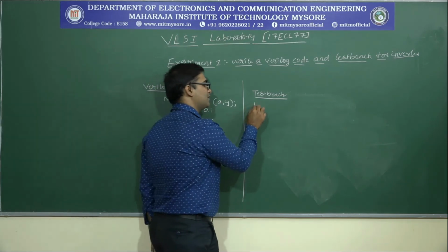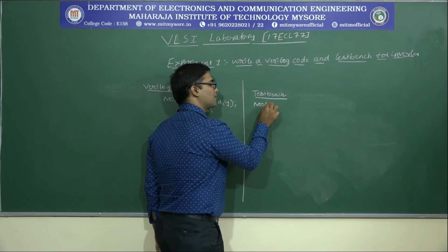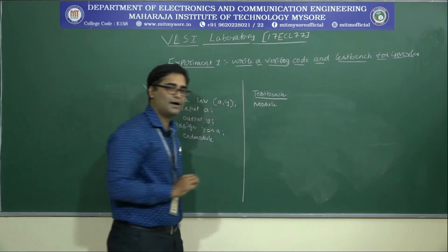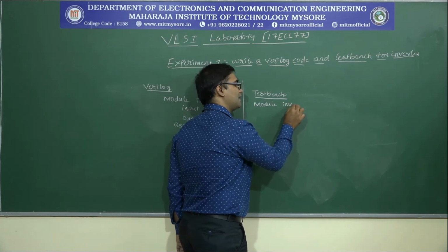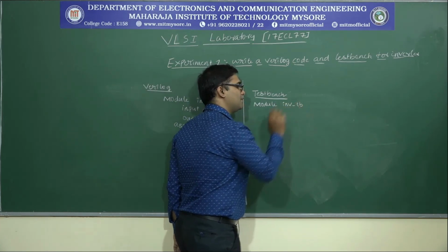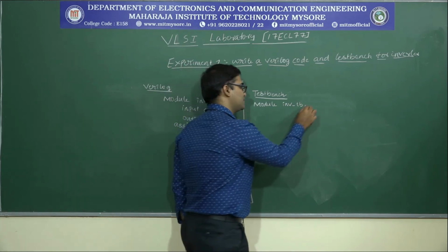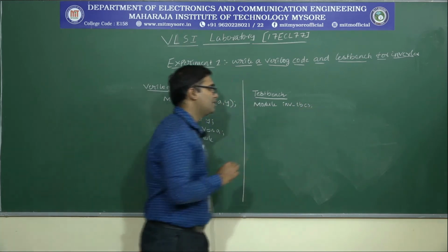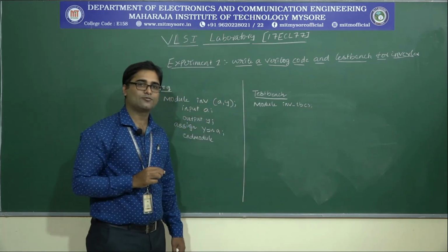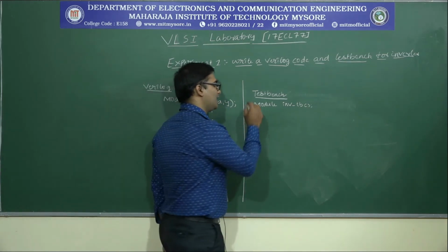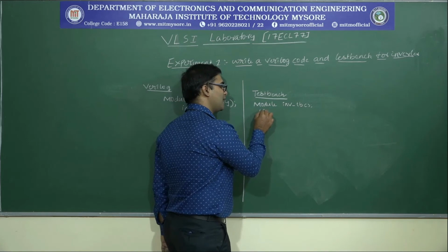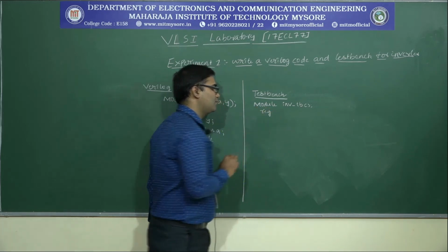It starts with module, followed by the module name. We will define it as inv underscore tb, which is called the test bench, followed by the inputs and the outputs, what we called the port declaration. In writing the test bench, we are defining the inputs